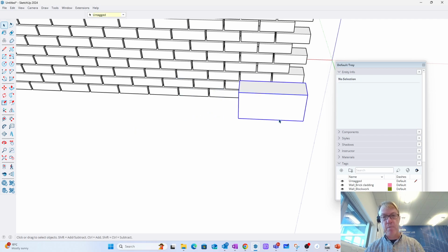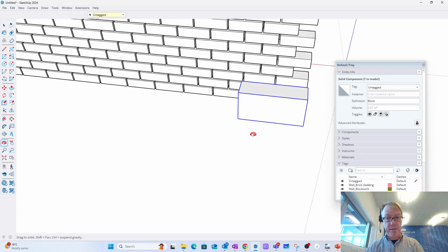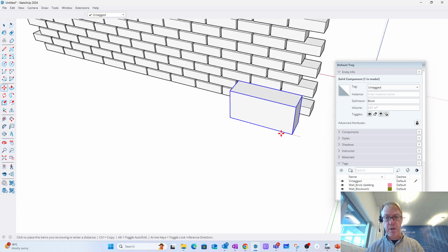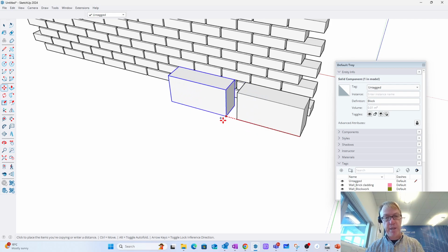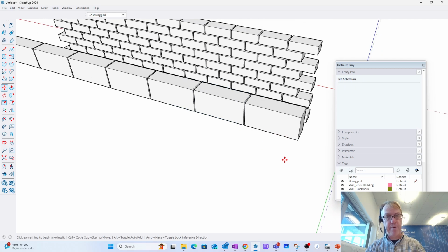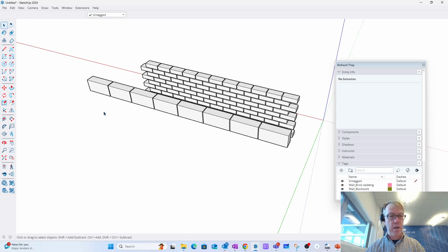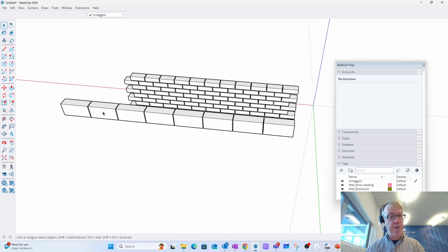Okay, I'll do that again. Might have messed that up. Select the block, press Move, press Control, keep the original there, press the right arrow key, 450, Enter, X7, Enter. Okay, it should have been X5. I'll remove the last two that I didn't actually need.